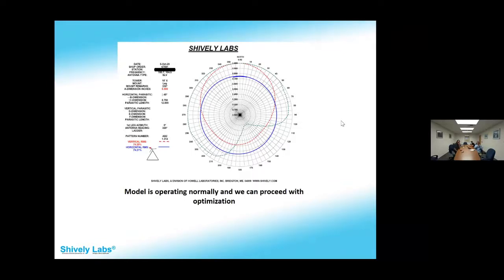Recently, we did a pattern that was on a Valmont antenna sandwiched between two halos, and we found that it had very little effect on the main lobe. The difference between having those halos there and not having them there was maybe a 5% difference. But what we learned through the process is it was the side lobes that were being reflected back. And by changing the position on the tower, we were able to minimize that. So that's something that we couldn't have done in our field measurements.